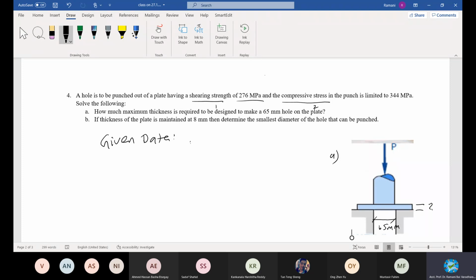Let's do this one. Write the given data. Same procedure. Can you all work with me so that we can check the answer one by one? You are given the normal stress or the compressive stress. Compression and tension are normal because they are perpendicular to the surface on which they are acting. On the other hand, shear stress is tangential or parallel force over area, hence it will be parallel to the area of application, or point of application. Please remember this point, right?